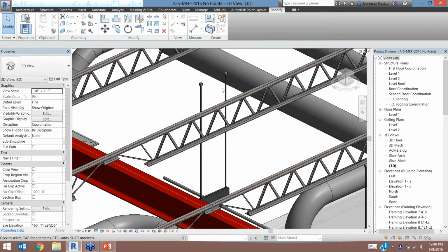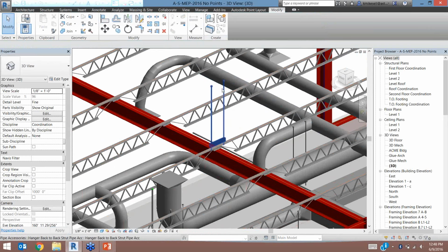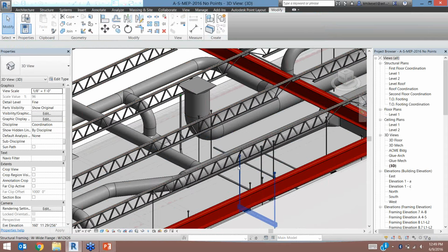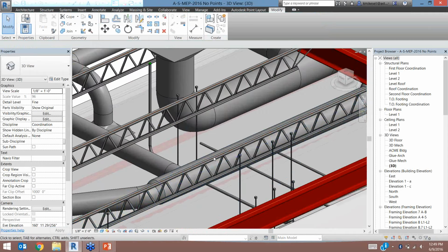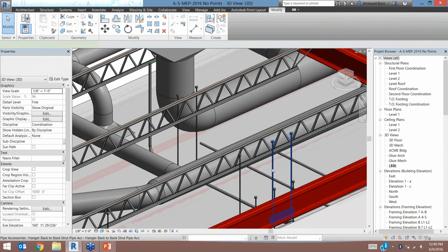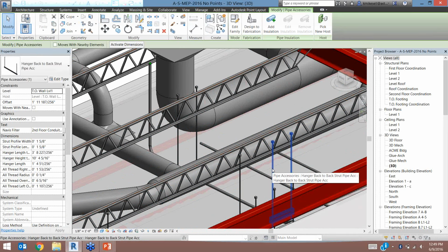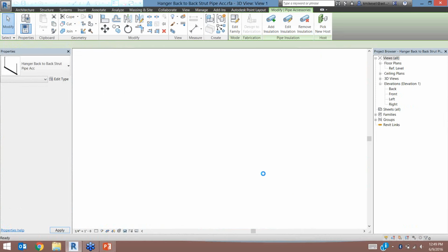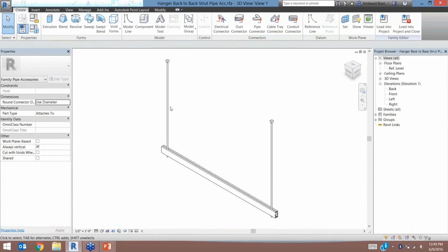And here they are. And we can look through and see that these hangers are different widths, and the points are still associated with the tops of the bars. Now sometimes on these hangers, instead of 2 rods, you have 3. Well, having an extra family for that 3rd rod can be a little bit of a nuisance. So what we're going to do is go ahead and make a parameter where we can add or remove that 3rd rod from the family.